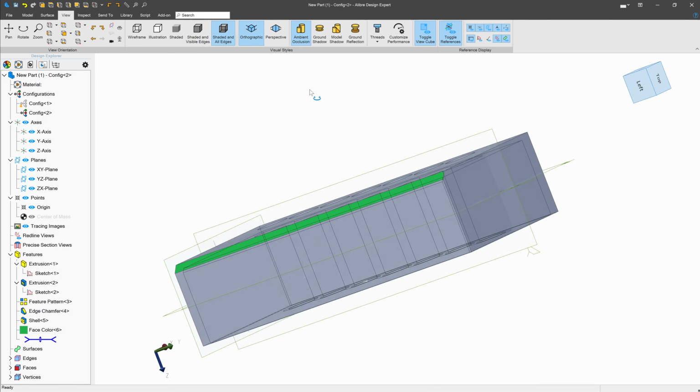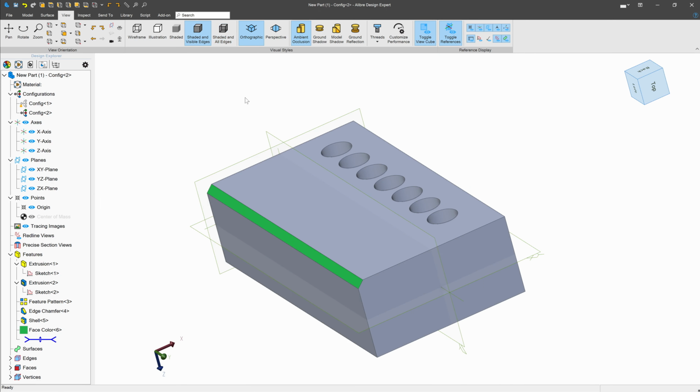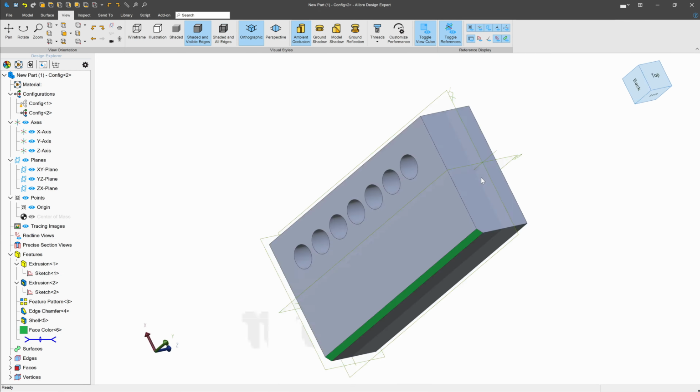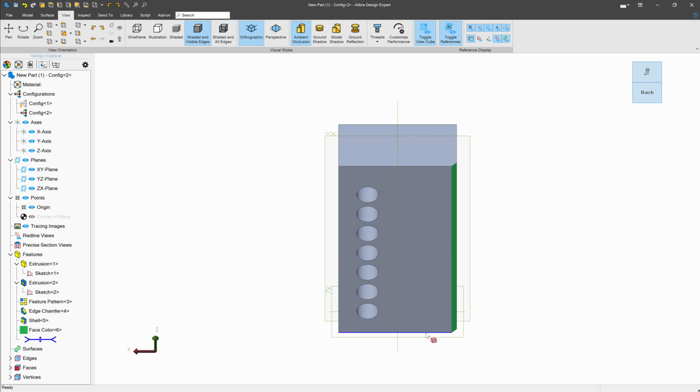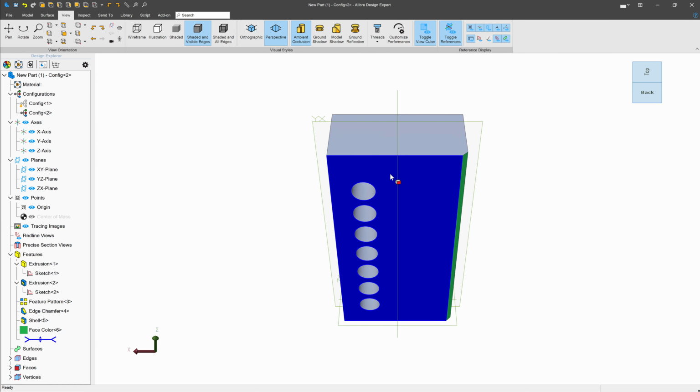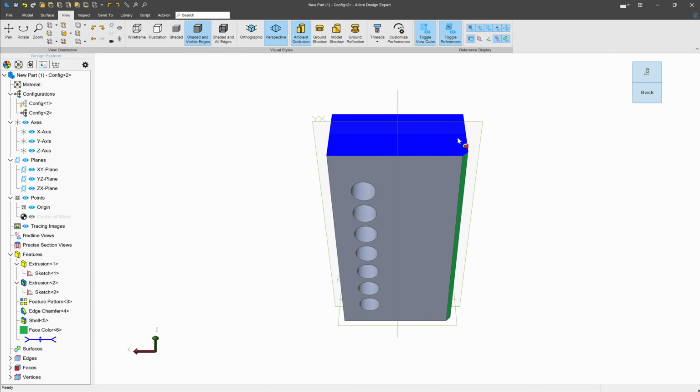Likewise, I always prefer orthographic. Orthographic means that this face is closer to me than this face, but these lines are vertical. Now, if I were looking at this with my eyes, this would appear slightly larger, and the face that's further away would appear slightly smaller. We can change that to perspective, and there you can see how this face gets a little bit larger, and as it moves away from us, it appears smaller.